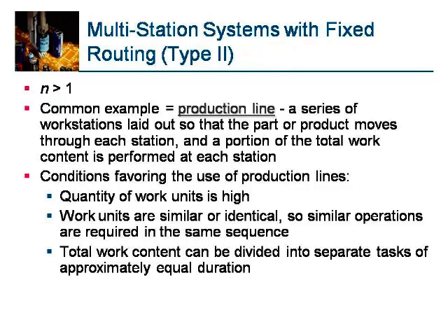Conditions favoring the use of production lines. Quantity of work units is high. Work units are similar or identical, so similar operations are required in the same sequence. Total work content can be divided into separate tasks of approximately equal duration.